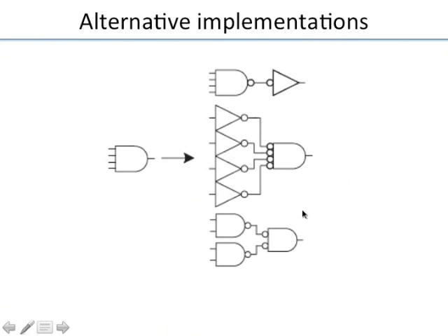What is this gate? It's a NOR gate, right? Because it's really a NOR gate. A NOR gate has an OR followed by a bubble in the output. You push the bubble in, essentially apply De Morgan's law, and it converts into an AND with an inversion at the input. So now you have these possibilities.